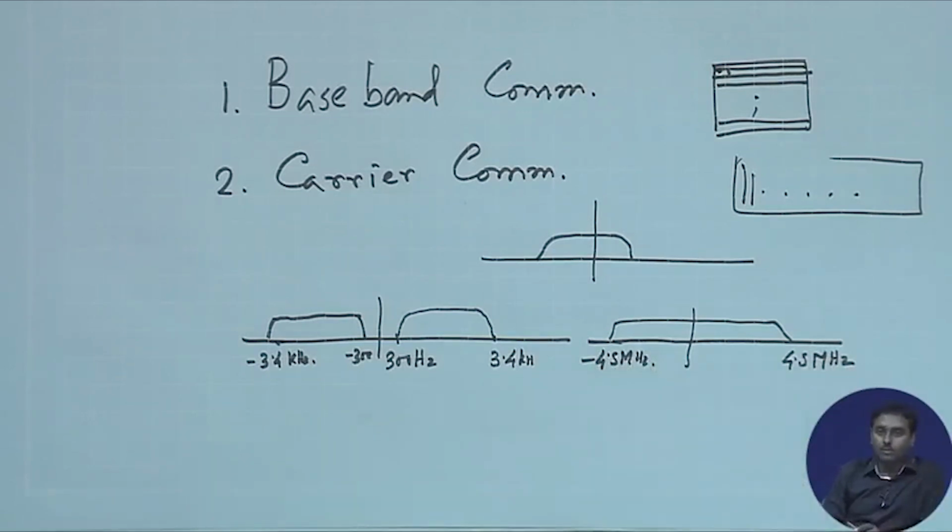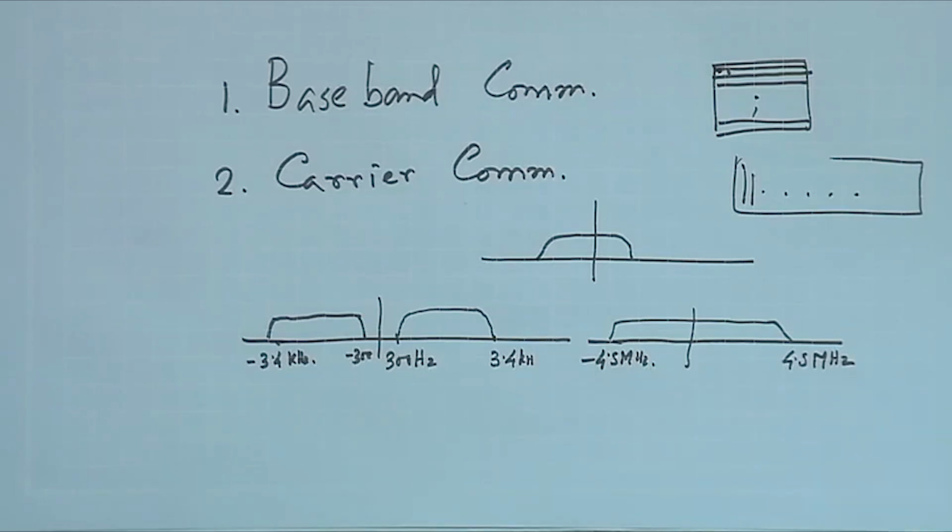Okay, so that's quite big. Of course, the video signal has a higher bandwidth, or it occupies a higher bandwidth. So this is the raw video signal. As you can see, these are all low pass equivalent signals. Okay, so it's centered around 0, and through a low pass filter you can always extract that signal. So the low pass filter bandwidth has to be accordingly adjusted.